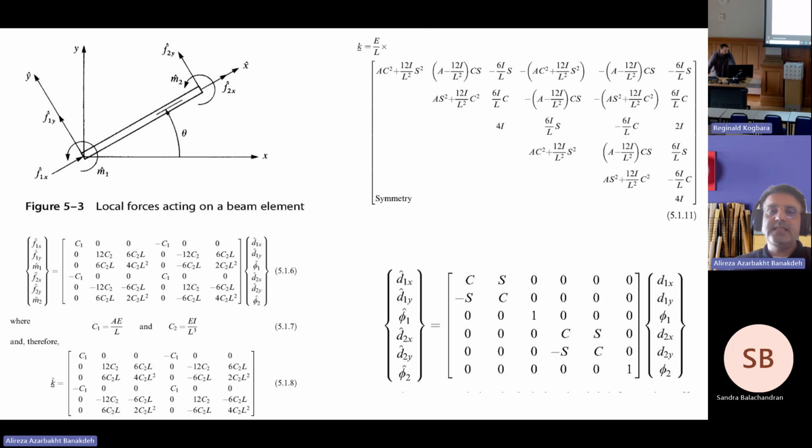I admit that it's a little bit confusing, and let me calculate both ways and record a short video and send it to everyone shortly. The point is you can use this one for the global coordinate system calculation, or this one for the local coordinate system, and both should represent the internal forces for each element, but in two different coordinate systems.